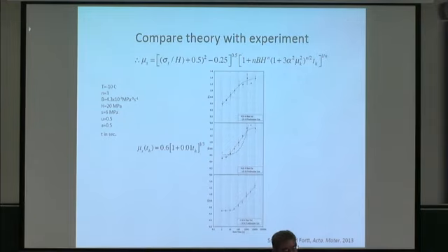And we believe that the contact stresses are probably well beyond an MPa, but we use that number anyway for simplicity. We also use the creep parameters for bulk ice. Well, is that the same parameter for an asperity that's 30 micrometers in diameter? We don't really know, but we have nothing else to go on, so that's what we use.